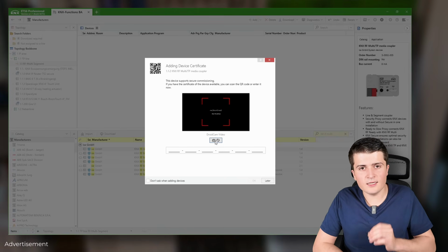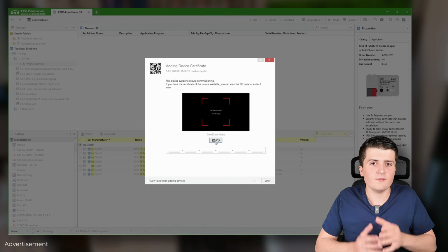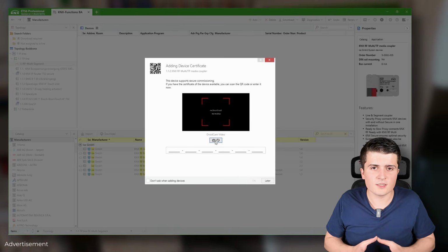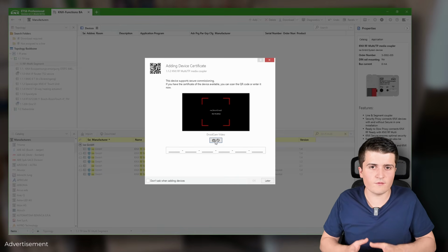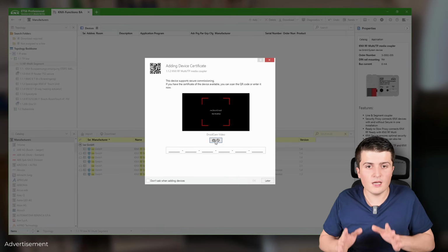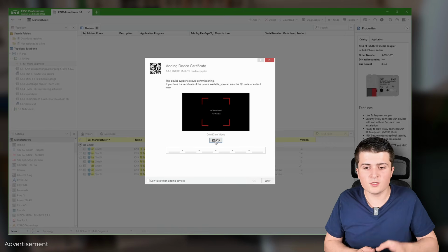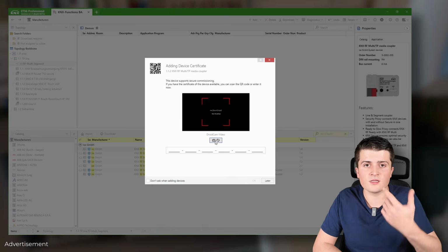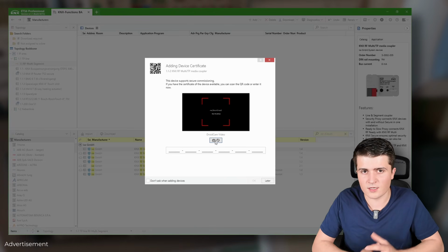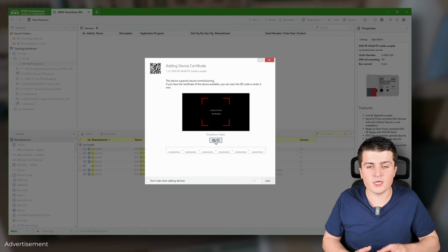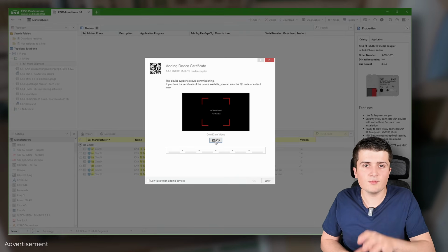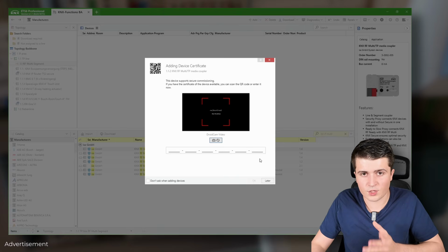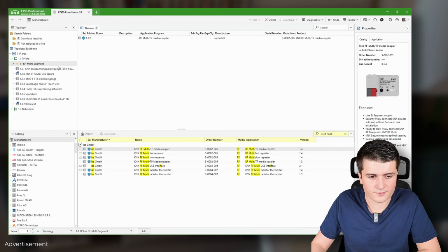Now in my case, I don't want to use KNX Secure, because for the purpose of this video recording, it makes it a little bit longer to download the devices. So therefore I'll stick to the plain communication, but make sure if you want to use Secure, then simply enter the device certificate here. It also has the advantage that you can then program the device via serial number. So in a normal project, I would definitely enable this secure communication here and add the device certificate. Because I don't use it here, I'll click on later.